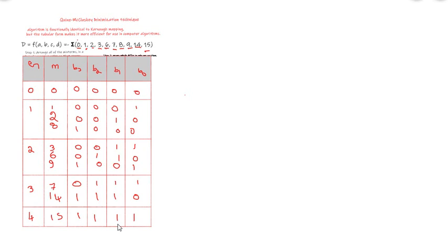So table 1, listen carefully. This is step 1, what we have done. We grouped the minterms by the number of ones present: the number of ones being 0, 1, 2, 3 and 4. There are 10 minterms given in total. Among these 10, the group with 0 ones has only one member, that is 0. The group with one 1 has 1, 2 and 8. See, the 1 is present in B0 for minterm 1, in B1 for minterm 2, and in B3 for minterm 8. In a similar way, 3, 6 and 9 contain 2 ones, 7 and 14 contain 3 ones, and 15 contains 4 ones.